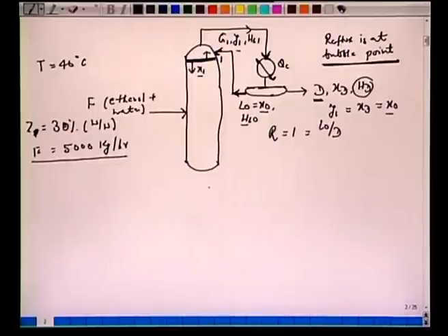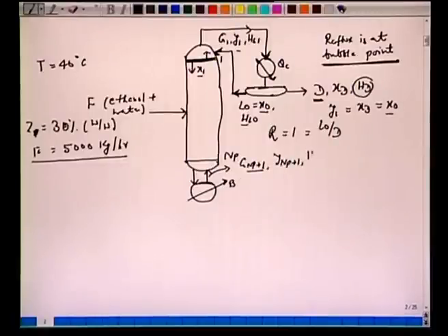All right. Now we have this bottom product. The liquid which trickles from the top, part of it is vaporized and sent back to the last plate, which is NP. So the specs for this vapor would be G NP plus 1. NP plus 1 stands for a theoretical plate for this boiler. Then we have Y NP plus 1 and we have H G NP plus 1. And this vapor now will be in equilibrium with the bottom product W, mole fraction XW and HW.